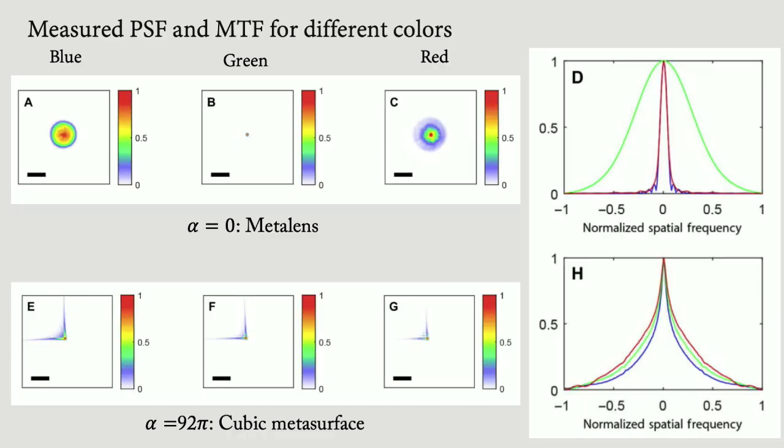But this is where the problem becomes important for the blurry ones. You get a lot of zeros here. Zeros are bad because zeros you cannot invert. Zeros essentially mean you are not capturing any information at those spatial frequencies, and that's why if you have a blurry image, you cannot completely recover the image without some prior knowledge. With prior knowledge, you can do that, but without any prior knowledge, you cannot get back this image because you are not capturing that information.